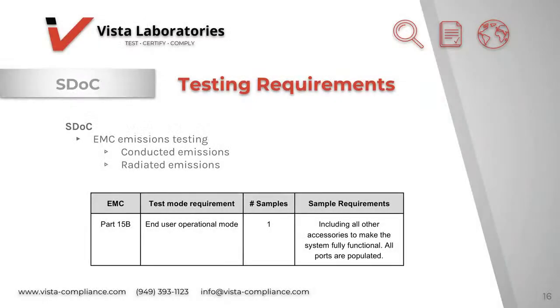Here's a look at the testing requirements for supplier declaration of conformity. EMC emissions testing will be performed. Immunity testing is not required in the U.S. At least one sample in end-user operation mode, including all necessary accessories, is required for Part 15B EMC testing.